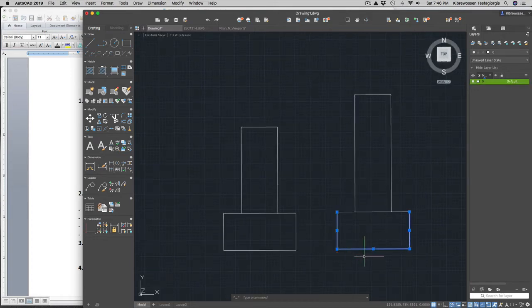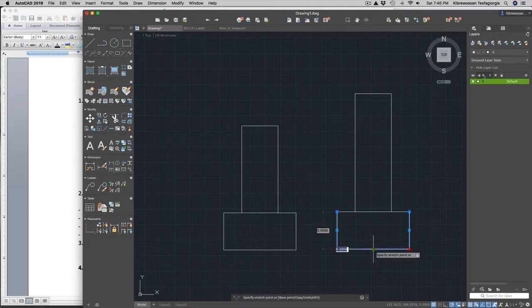See, then okay, then I select this line, select that line, select that line, press the shift key and turn them on, and then I can click on the middle one and move this by 1, then the dimension is stretched by that amount. Okay, so the overall exercise is how to exploit the grip option.